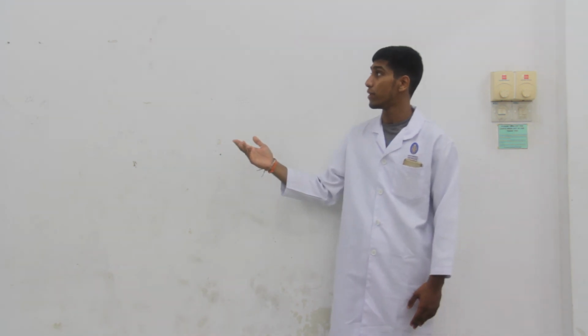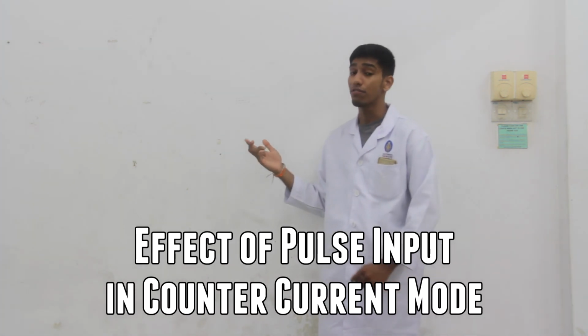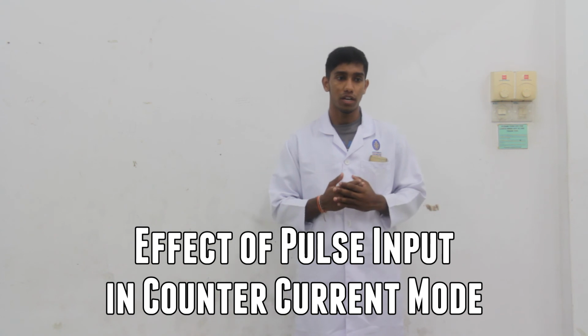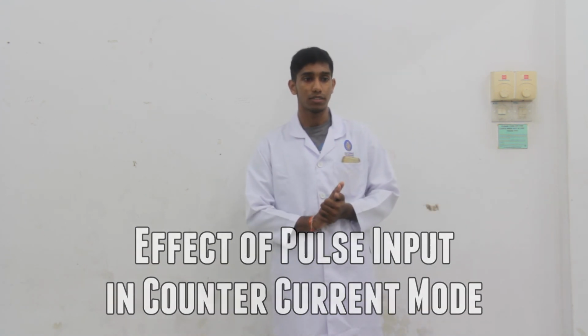Now we shall proceed with experiment B. In experiment B, we will study the effect of pulse input in co-current and counter-current mode. First of all, we will see the effect of pulse input in counter-current mode. The liquid flow rate and the air flow rate are kept constant, which is 0.05 LPM and 1.0 LPM respectively.